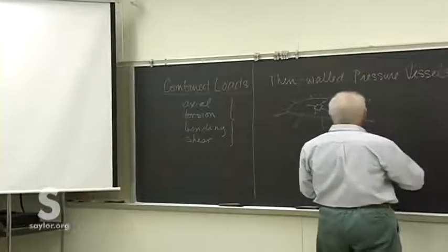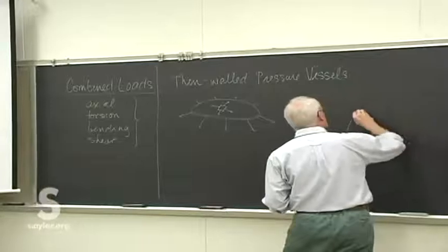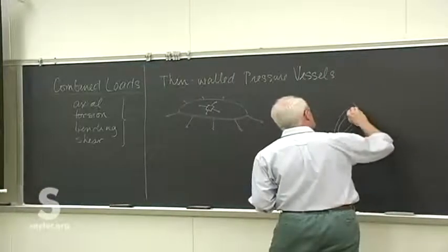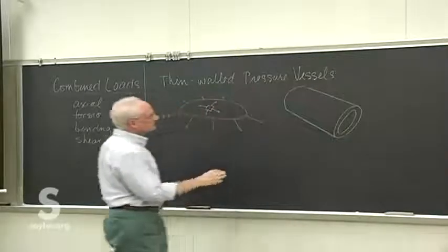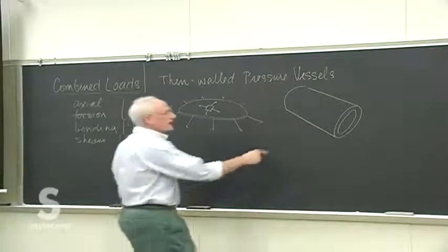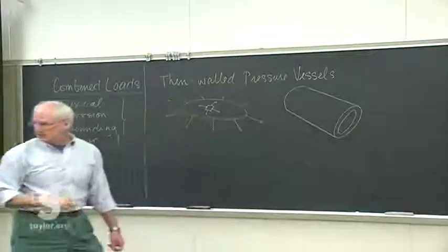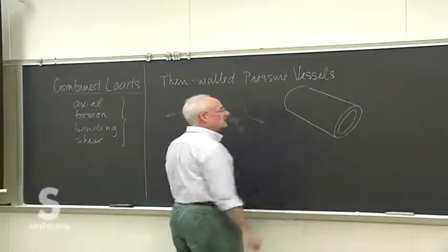So to be a little more specific now, we'll start with a look at a cylindrical pressure vessel. So we've got it in cutaway. Of course, it's got some kind of cap on the end. High pressure vessels don't do well if you just put a flat piece over the end, because as I just mentioned, there's no resistance to bending of these very thin materials, and that end cap would be almost entirely in bending.